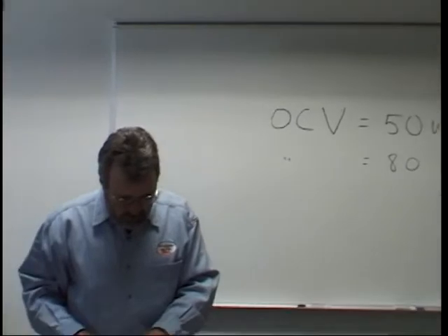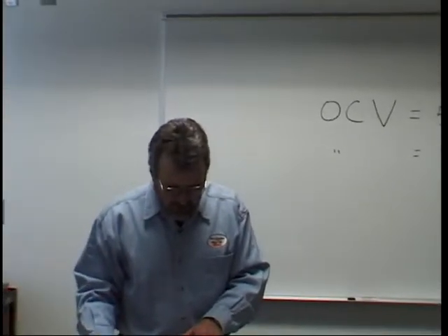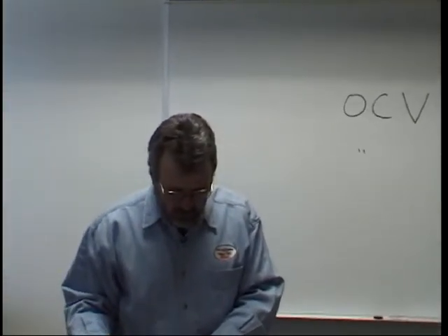So once the voltage has been set, the machine automatically maintains an arc length while the electrode wire is fed continuously at a set speed. Changes in the filler metal, shielding gas, or granular flux may require a voltage adjustment because you're adding different types of elements, different masses involved with these elements. You may have to change that slightly to compensate.